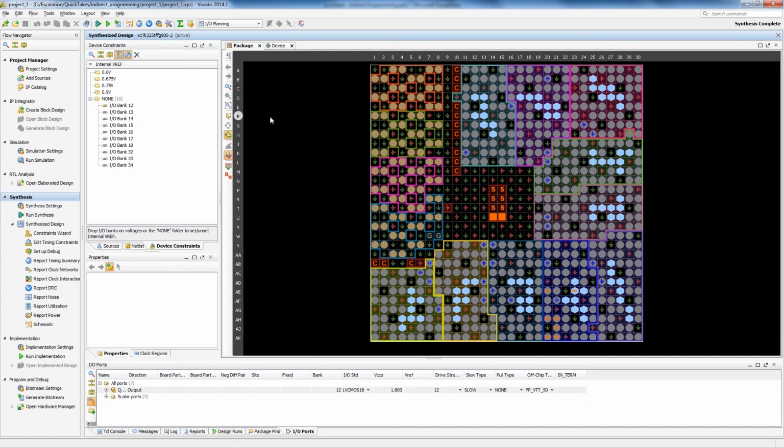Now let's take a look at a demonstration of indirectly programming an FPGA. In this demonstration, I'm going to reprogram a BPI configuration memory that is available on the KC705 demo board. I've already set the correct dip switch settings to ensure that it is put in the master BPI mode. I have a simple counter design here that I have run through the synthesis phase.